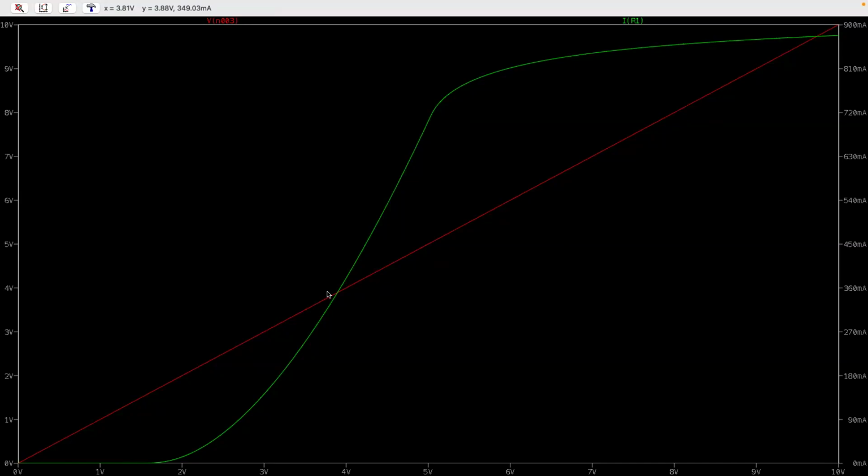You can bias it here, but then when you change this voltage with a sinusoid, you're going to be moving up and down this curve, and it's going to increase your harmonic distortion. Because when you try to go down a certain amount, it'll go down more or less than you expected. Similarly, if you do it up there, it'll go up less than you expect when you try and go up. So if you bias it right in the middle, then you can swing your signal all the way down here, and pretty much all the way up to there, while still getting a linear response.